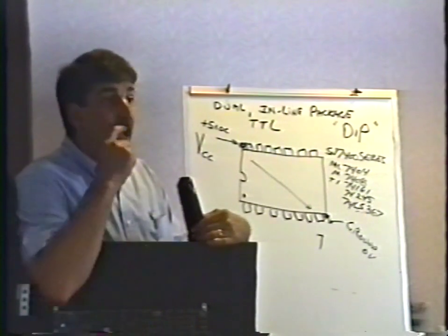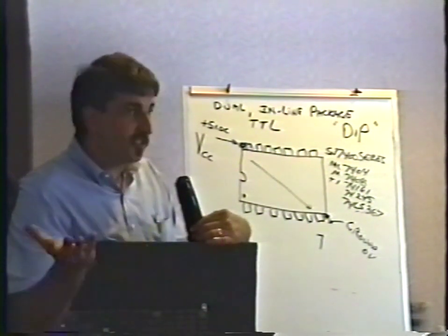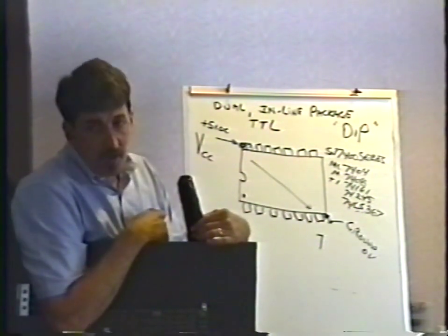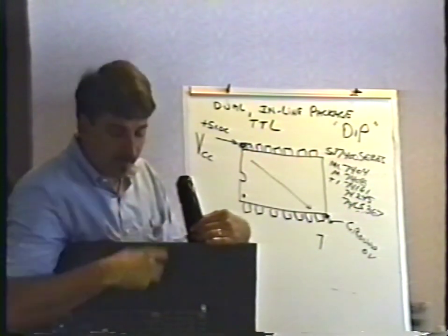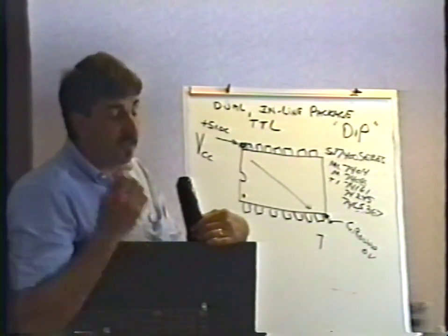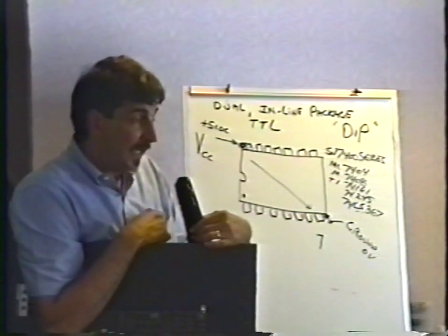Sometimes power supplies put out a huge amount of electrical noise that your meter just doesn't see. An oscilloscope would see it, but your meter doesn't. When you have weird problems on the board like the one I just showed you, despite the fact that you might measure the 5 volts and it might be perfect on the board, it's not a bad idea to take 10 minutes and throw in a new power supply first.